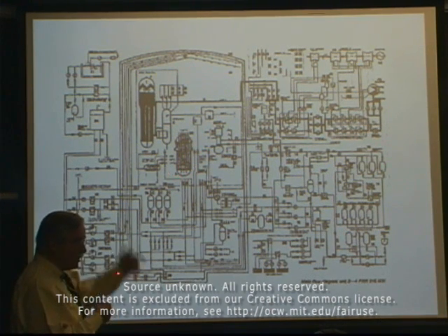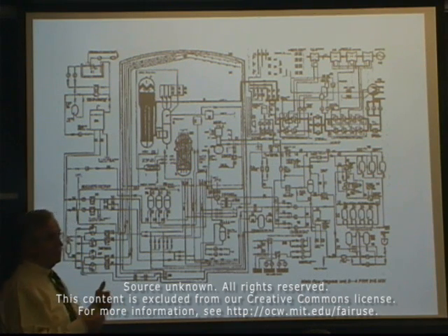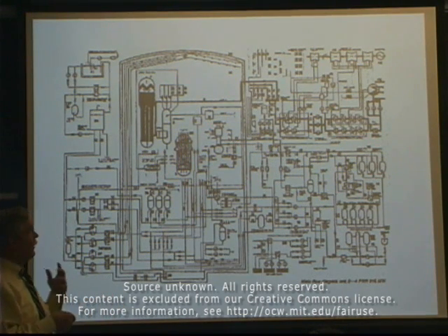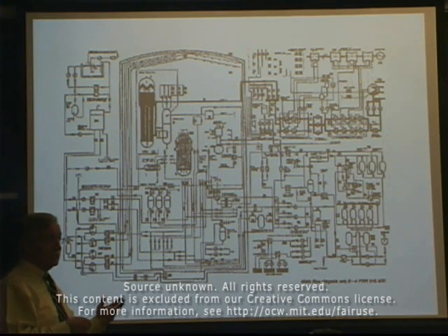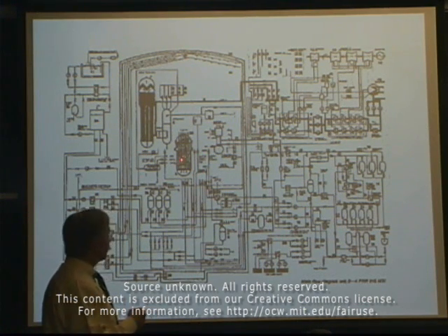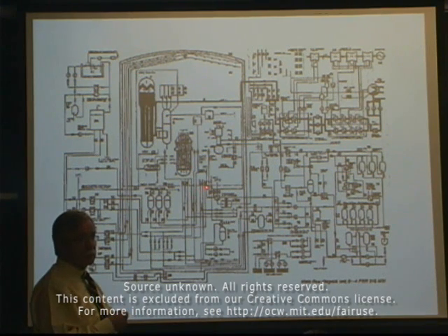So we'll start to think like an operator, like an engineer who says, what is my most important function here in this reactor? And that's easy. We have to keep water there. Because if we don't have water here, you're going to break barriers. That's the most important thing.